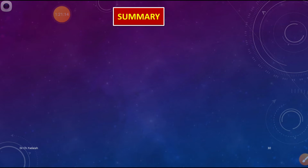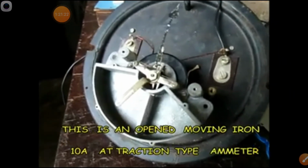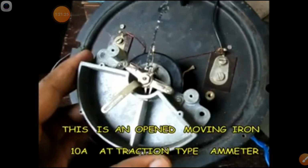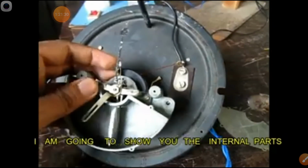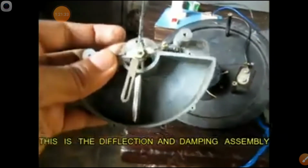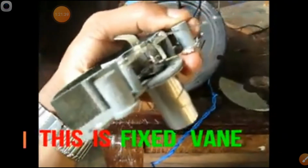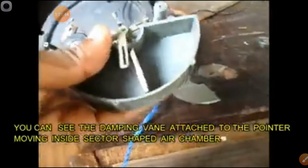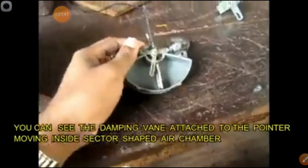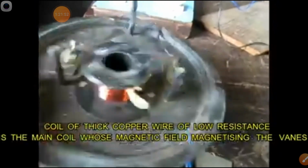Okay. So, dear students, now I think the time is more. Now, you can see one practical instrument. This is an opened moving iron instrument. You can see this is for fluid friction damping, and we have taken out the pointer for adjusting purposes. There is a fixed cylinder type iron piece. If you remove that one, there is a coil present inside. So, you can see the coil on the other side. This is the coil connected here.